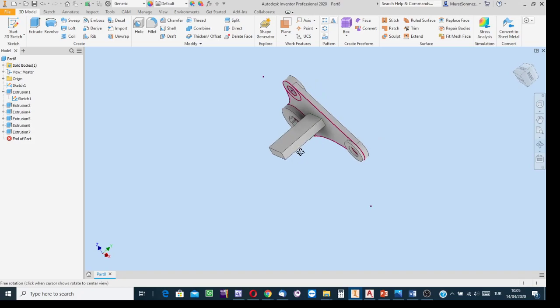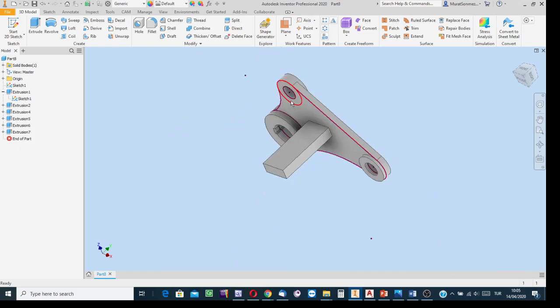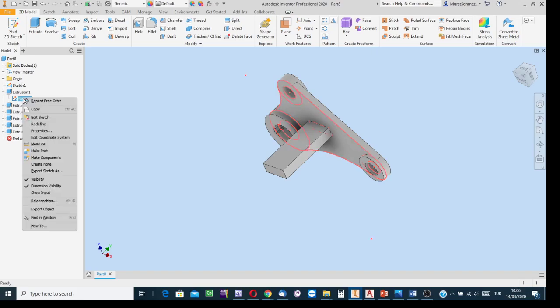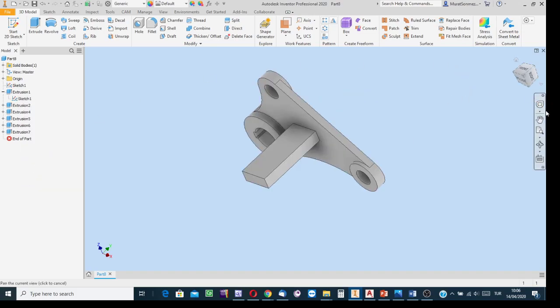If you ask for the visibility of a sketch to be able to reuse it, then the sketch is still shining on the screen. It is not so good. Find the same sketch icon and take its visibility off the screen. How? While the cursor is on that sketch icon at the browser, right click the mouse and deselect the visibility option. This is good practice.